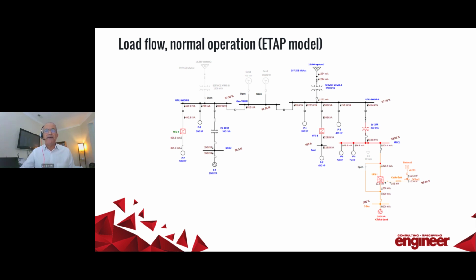This is actually one of the types of UPS that Nicole pointed out, the online or double conversion UPS system. Now, if you look at it here, the voltage on the secondary or the output is controlled and is 100%. Therefore, that load flow provides you not only the amount of power that you need to size the UPS, it also provides what the feeder and circuit breaker should be sized on, based on the worst-case possibility: the amount of power, the current going through the system, including the voltage at the output.